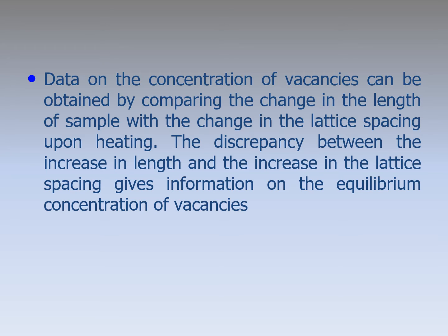Data on the concentration of vacancies can be obtained by comparing the change in the length of a sample with the change in the lattice spacing upon heating. The discrepancy between the increase in length and the increase in the lattice spacing gives information on the equilibrium concentrations of vacancies.